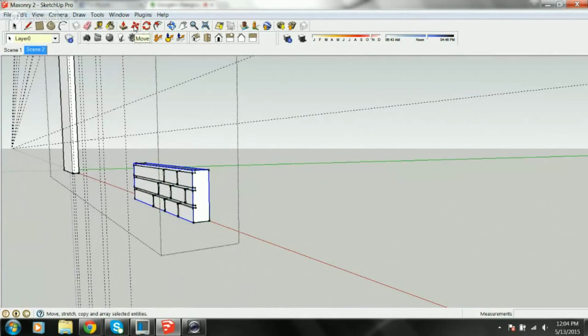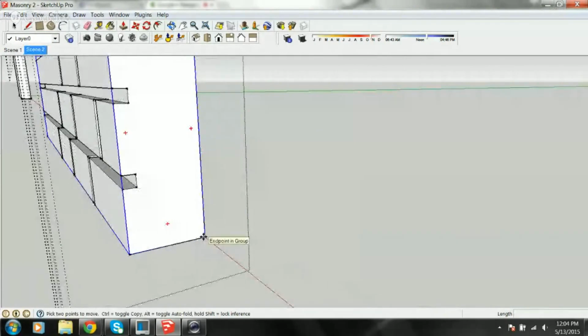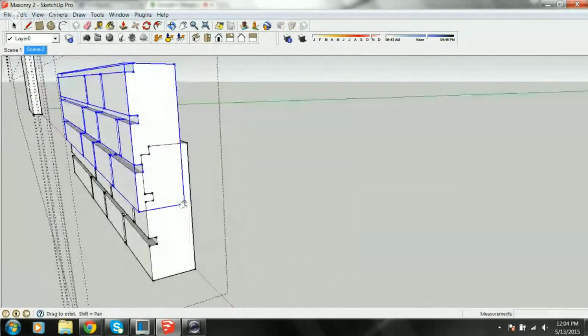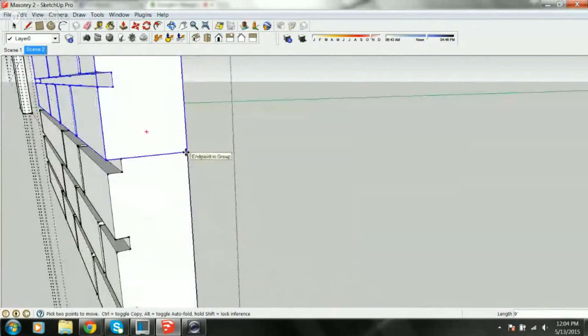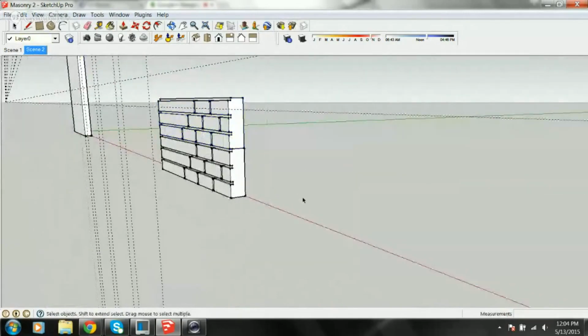I'm going to click on the move command. In my model, I click on a bottom point that I know is a real point in space. Pulling it up. Where do I want to align it? Right there, because I've got my groove. However, this would give more planes to the model.